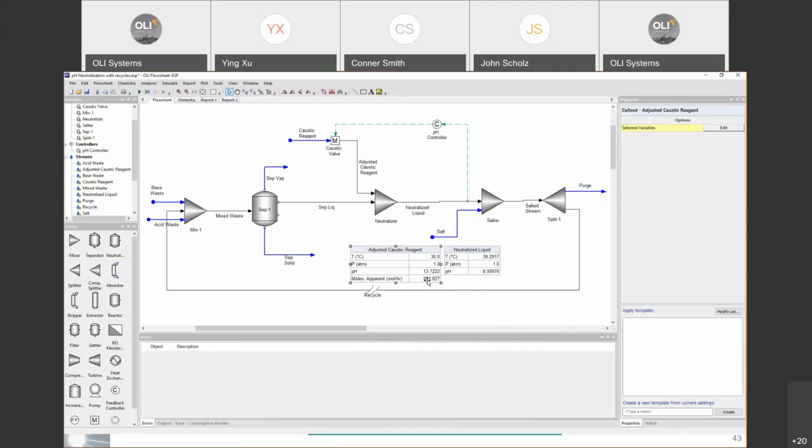And the reason is maybe that some of the unreacted caustic that we had in this neutralized liquid went back here, and now we are reusing it. So we don't need to use as much of this original caustic reagent, because we are reusing what didn't react after we made the neutralized liquid here, right? Hope it makes sense. We added caustic reagent, maybe not all of it reacted.